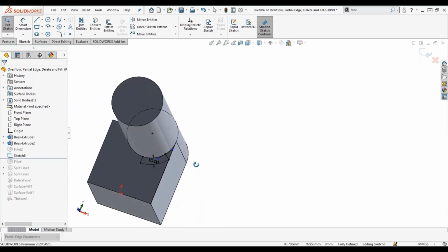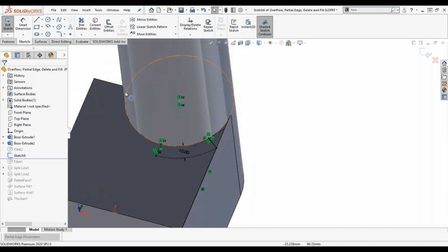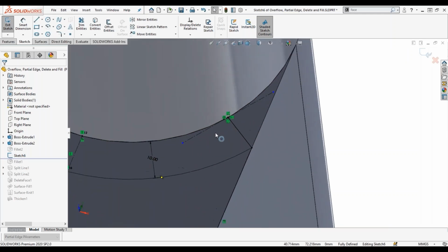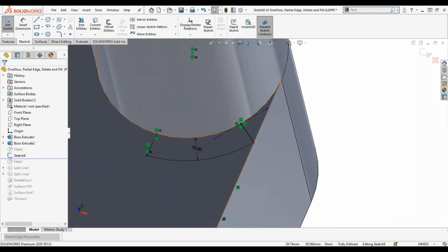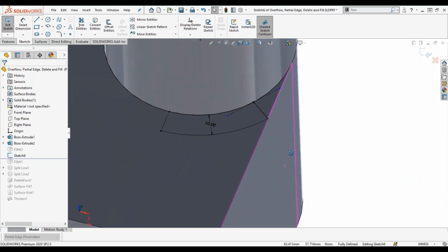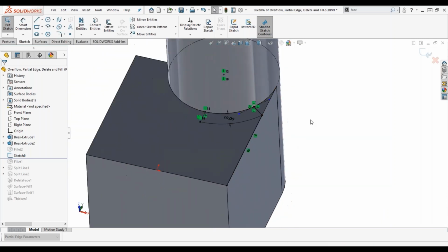So I knew that as this edge comes around, as that fillet comes around, it messes up right at this intersection. And I know that I want to add a constant size, circular profile, symmetric fillet that is 10 millimeters in radius. So that edge that it's going to create is just going to be 10 millimeters offset from this edge. And I found the point that it's going to intersect. Not necessary to use this tool, but it's going to help us, and I'll show you why.